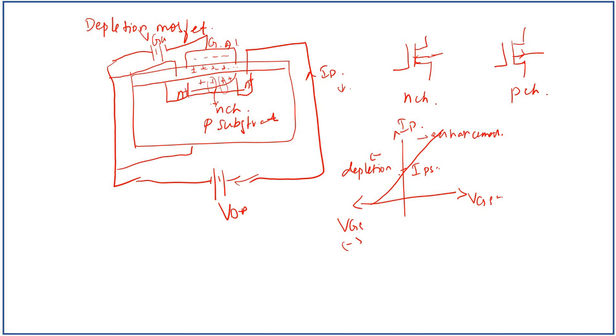Handling precautions of MOSFET. MOSFET is very susceptible to overload voltage and may require special handling during installation. It gets damaged easily if not properly handled. The thin SiO2 layer between the gate and channel is damaged due to high voltage and even by static electricity from the human body.